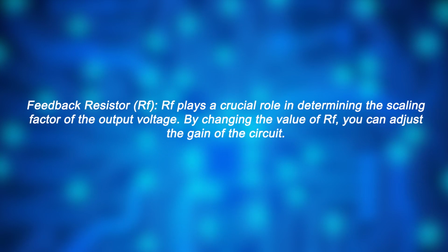The voltage from each source is applied across its respective resistor. The next is the feedback resistor. The feedback resistor, labeled as RF, is connected from the output of the Op Amp to the inverting input terminal. RF plays a critical role in determining the gain of the Op Amp.